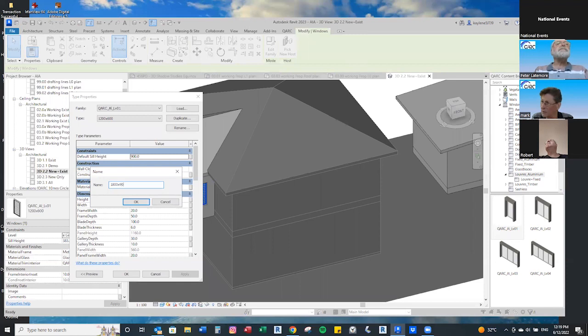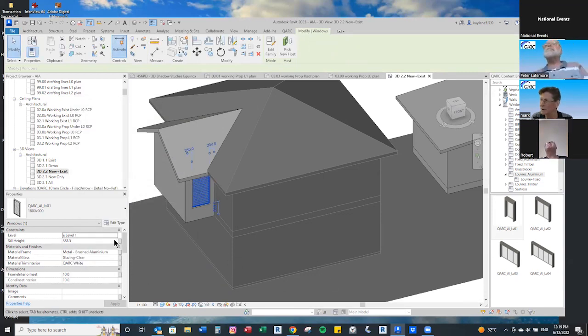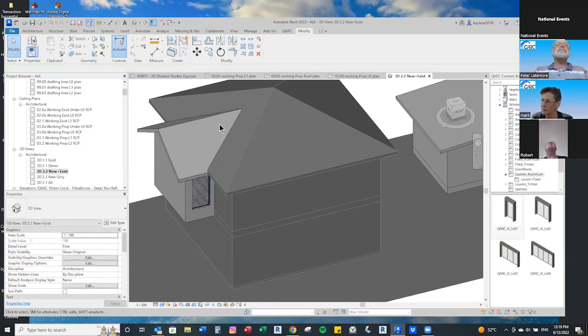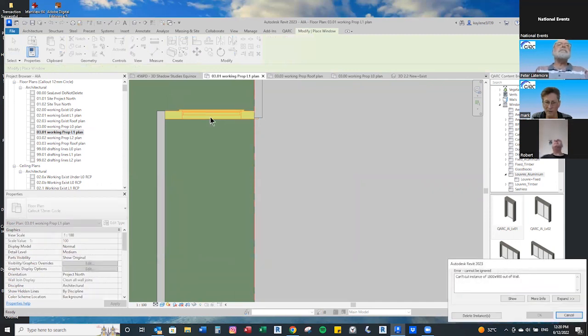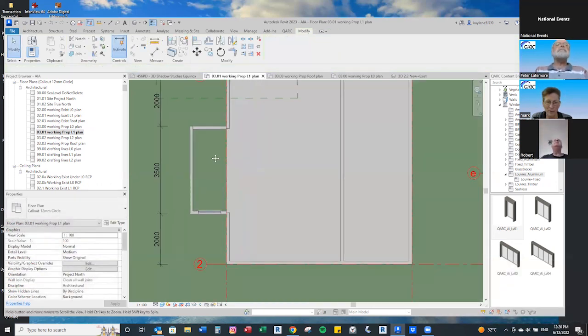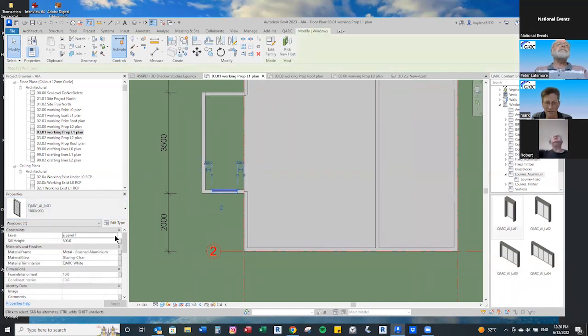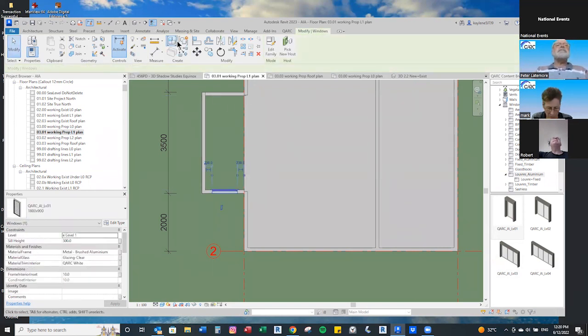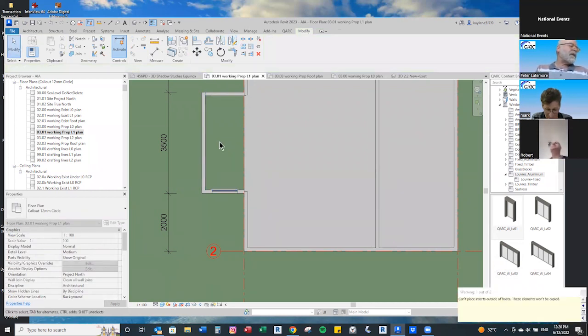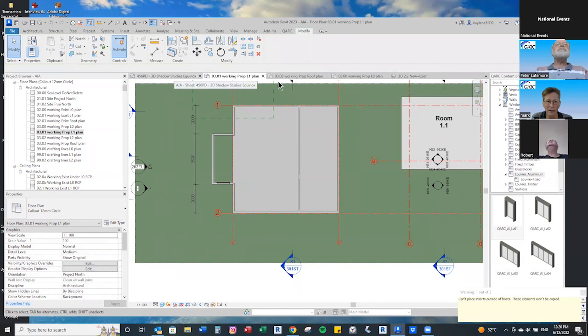The other important thing is a lot of the manufacturers you'll actually notice, if you're a practitioner like we are, over model stuff. So for example, a lot of window and door manufacturers model down to the last grommet and screw and fixing, sliding door windows. So when you actually print that 1:100, it comes out as a great big black blob, because one of the problems with Revit is you can't make thin lines so extremely thin that at 100 blow up, they don't read correctly. So I get frustrated all the time, get all this manufacturer's Revit files, which are just absolute rubbish. And they don't understand. Beautifully modeled, but no use to us, because we want to actually show that it's a window, not a big black blob. So that's long way to go on that, I'm afraid, when it comes to manufacturers.